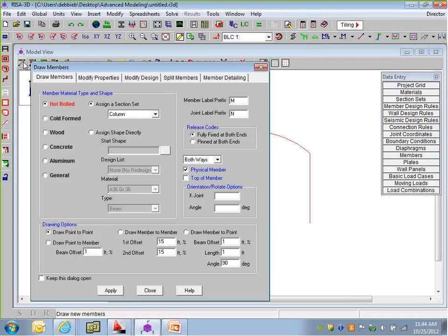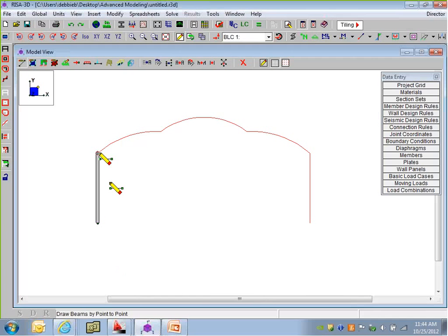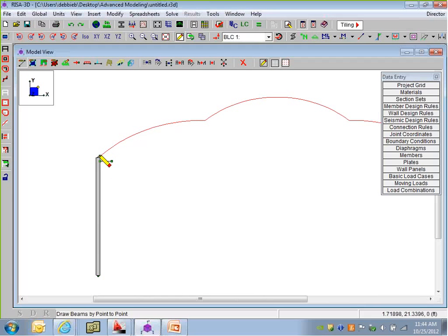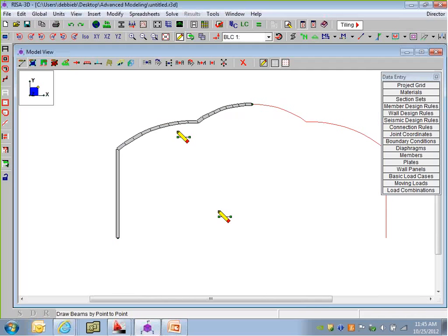And then I'm going to draw on that the arc. Okay, so I'm going to say the arc there. I'm going to be able to draw on this arc. Now where I can click to is every 5 degrees. That's because that's what I told the program to import that arc in as, 5 degrees. So you can go lower, you can go higher. That's adjustable for whatever you selected there. So I'm going every 5 degrees, up, up, up there. And I'm going to hit the middle because what I want to do is a dome. So this is going to be 3-dimensional for me, not just 2-dimensional.